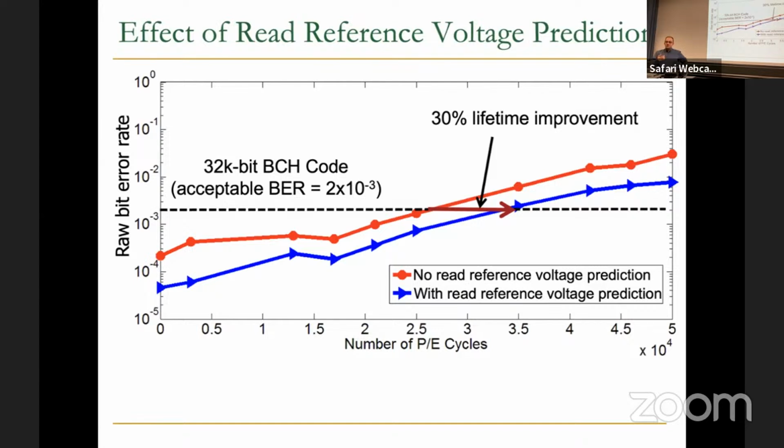So the idea is that with this kind of technique, you can predict the reference voltage better, such that you can access your flash memory and read well the first time. Even if you cannot get the result the first time, the second attempt can be much better. That's the main reason it also provides better performance, because you're reducing the number of read retries.